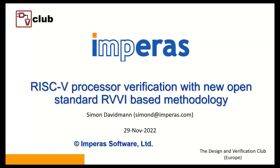but we're actually involved with CHIPS Alliance that is working on this as well. So Verilator currently supports the Verilog and SystemVerilog subset that's synthesizable. It does not do today the full SystemVerilog that's used for test benches, and so today you can't use Verilator for things like SystemVerilog functional coverage because it does not implement those things.